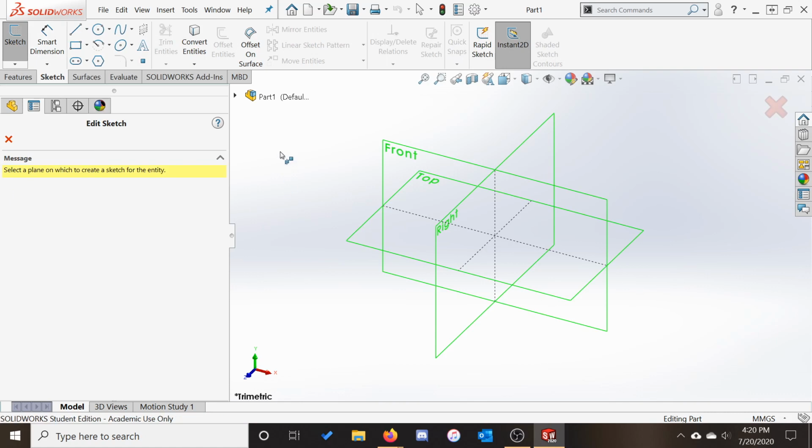From here, we must tell SolidWorks where we would like to sketch. You can sketch on any plane or a flat surface. You can also select the plane first and then hit the Sketch button. The two methods are equivalent. We don't have anything to work with yet, so we'll select a plane from our 3 default planes. I'm going to start drawing on the top plane.